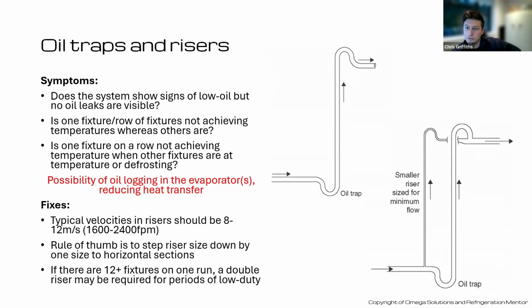Could still be loads of oil trapped in that section of pipework, down in those evaporators, coating them all. Basically, the more oil we have down there, the less heat transfer we're going to get into our refrigerant, because it just coats the surface of those evaporator coils. You'd need twice the airflow to get the heat into it, which those evap fans aren't going to change. So all you're going to get is half the cooling, and therefore it's not going to achieve temperature, and then you can get all of your alarms happening instead.